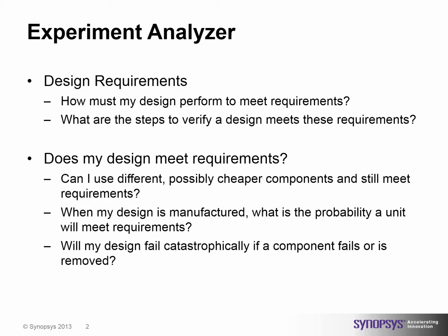This is useful not only at the beginning of your design cycle when exploring device sizing and optimizing component values to meet requirements, but also for exploring how the design will behave as variations are introduced by the manufacturing process or aging. Similarly, the experiment could be used to see if the design continues to meet requirements as components fail or are removed. If the design does not meet requirements in these conditions, the design can be modified to mitigate the effects of these failures. Let's take a closer look at the Experiment Analyzer in SaberRD.